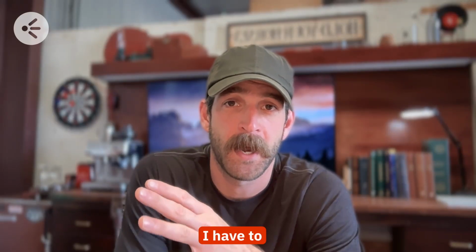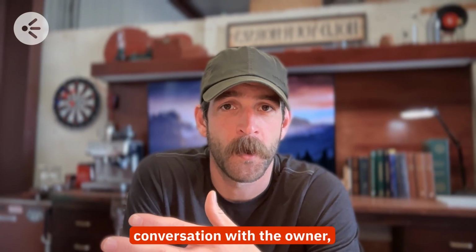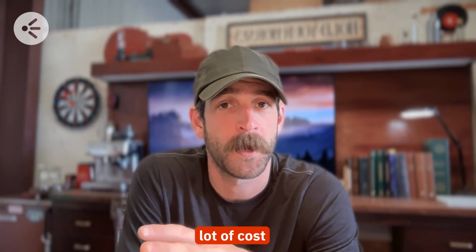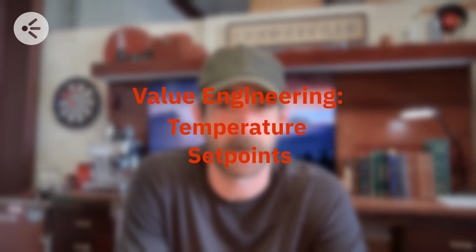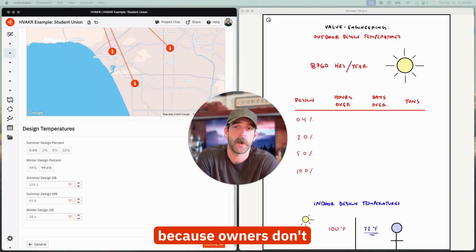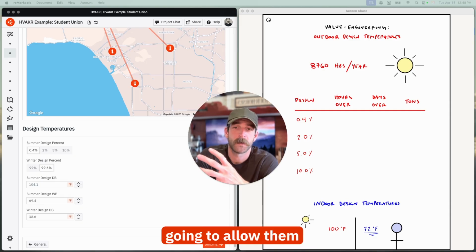When a project budget is tight and I have to do some value engineering, this is the first place that I look. It requires a real conversation with the owner, but if done right, can reduce a lot of cost with minimal design changes. I'm talking about outdoor and indoor temperature set points. The reason this is a good place to start is because owners don't fully understand the assumptions we make when sizing an HVAC system. So this is going to allow them to make an informed decision on comfort versus cost.